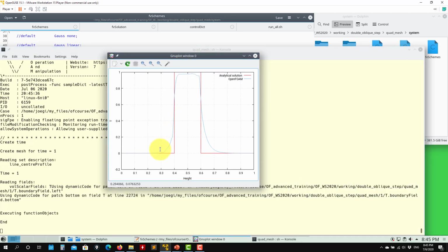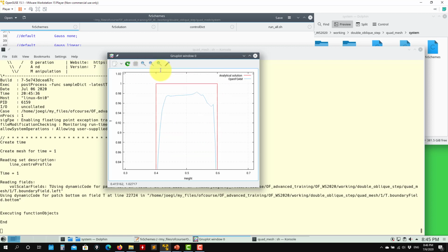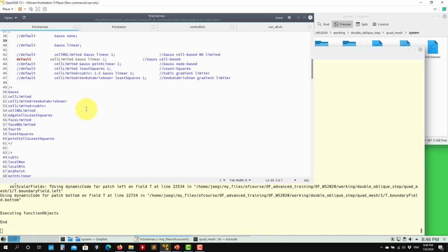So see that now you don't have the oscillation. There is some diffusion. It's not a very nice solution, but we know that we play with that with the time step. So maybe as we reduce it, we're going to get a better agreement. But the idea of that gradient limiter is just, when the gradients are being reconstructed, if the gradient is larger than the value of the neighbors, you will clip the solution to avoid that unboundedness.